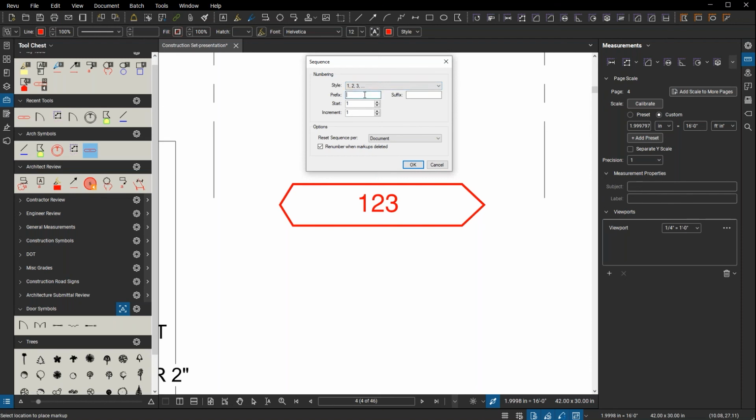You've also got the option for a prefix and a suffix. So if you want to always have a certain, it's a job number, it's job 1, 2, 3, and the numbering scheme is a dash 1, 2, 3, 4, 5. That's the part that actually will sequence and index through your numbers. You can choose. So I might want to have, here's my RFI. Start at 1 and maybe step by every 5, every 2. What might you change that to? That's up to you. If you want to go just 1 by 1, I'll step mine by 5 just for something different.